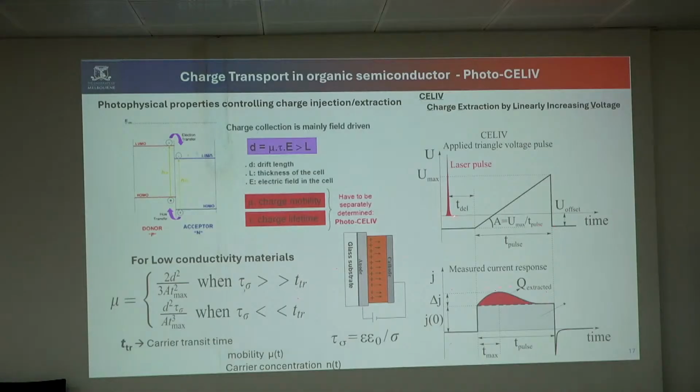During the course of time, we apply the pulse here. After a fraction of a microsecond, we start applying voltage from zero. This voltage can be a square potential, a linear potential, or a triangular pulse. We apply a triangular pulse because it increases linearly from 2 to 3 volts, or whatever the maximum voltage is, and then suddenly it stops.